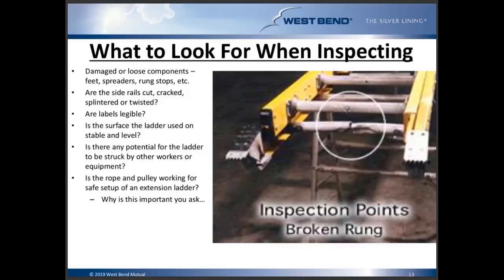Is there any potential for the ladder to be struck by other workers or equipment? So making sure that we're not setting up this ladder adjacent to an overhead door to a shop or an entrance to an office. We need to keep the ladders away from those areas so someone or something doesn't bump into them, especially while there are workers on the ladder.